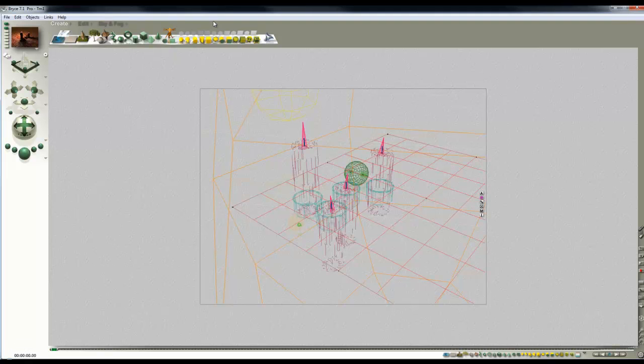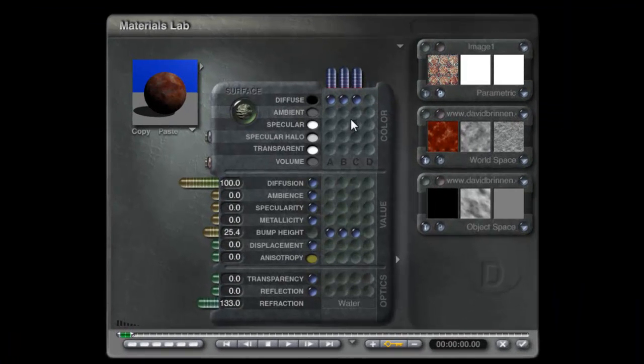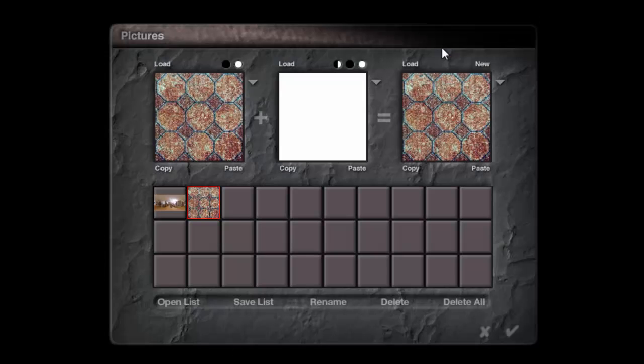So I've forgotten where that is. Oh, it's on edit, that's why. Right, edit, convert selection to 2D surface. I'm going to modify that 2D surface now, reset it, and set the diffuse to a picture, which it's already in a picture because that was previously loaded the carpet image.